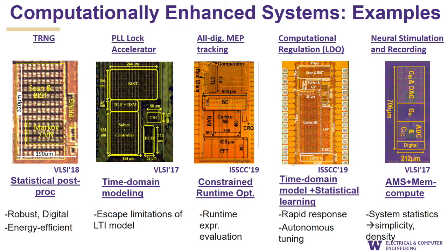Here, basically relying on a time domain model and very simple statistical learning, 1-bit statistical learning, you can basically auto-tune and auto-center an LDO and basically demonstrate the fastest LDO that's been built to date.